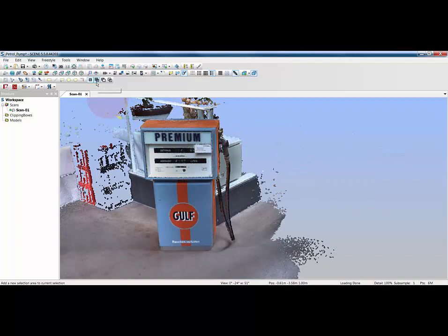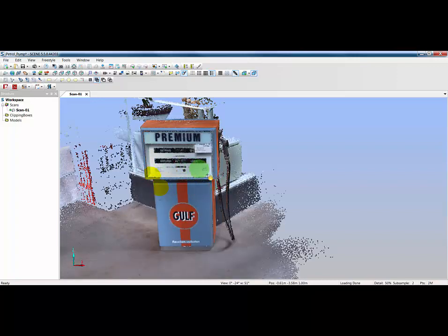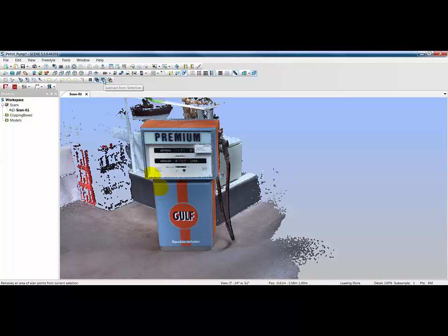Also, you can use the options up here for adding to the selection, or subtracting from the selection, or intersecting with the selection. Now to do this, all you do is highlight an area, and during the highlight it goes yellow, and if I then add to selection, you can see that my area then becomes green, and that's telling me that I'm adding to a selection because the selection area is green. If I want to subtract from the selection, the cursor then turns red, so I instantly know that visually I'm subtracting from that selection I've already made. Or we can use the intersection option, and then my cursor turns blue, so straight away we can see what areas we're selecting.